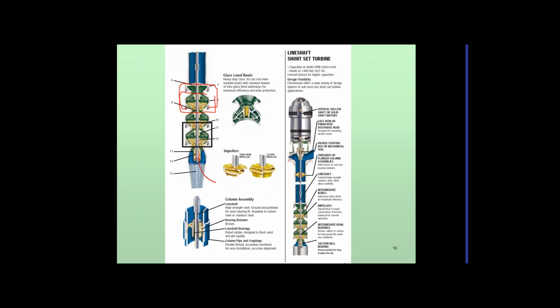So the water comes in the bottom, up through the first impeller, which puts work on it. That's the input for the second bowl, and work is put on that, on up through the third one, and then it heads up to the surface through the pipe that's attached, and the shaft running that comes down from the surface.